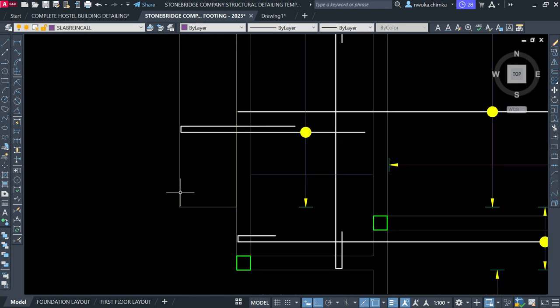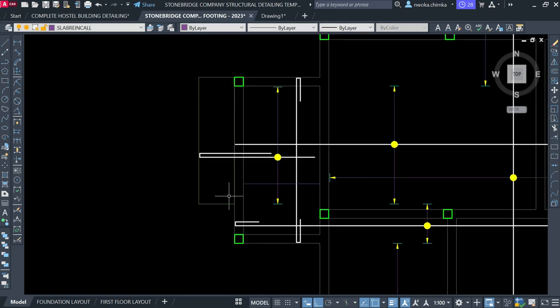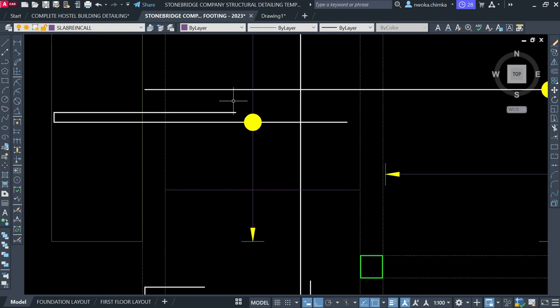It stops here. So I'll start on this other end of the beam and span to this place. Trying to cross here, it now finds a cantilever slab, which is not full, just halfway. So this bar also has to stop directly at this place for the next bar to continue, which is a straight bar. Okay, so now go here and copy this.